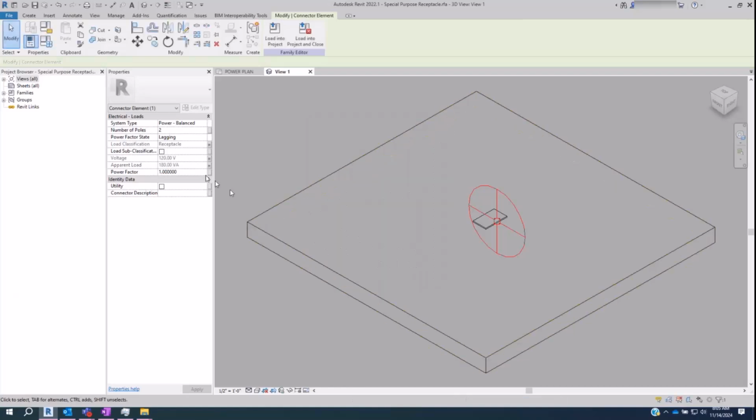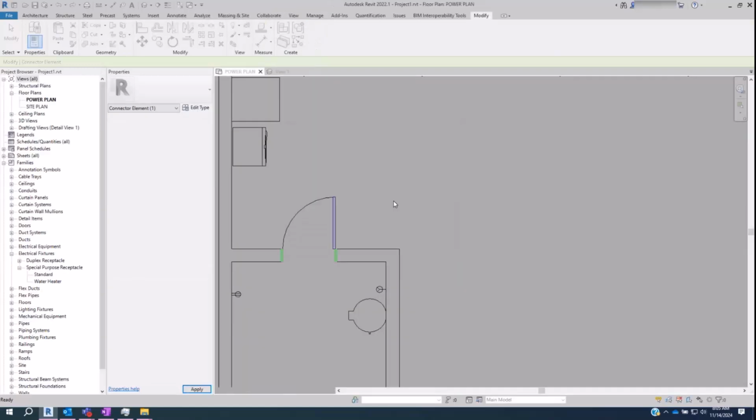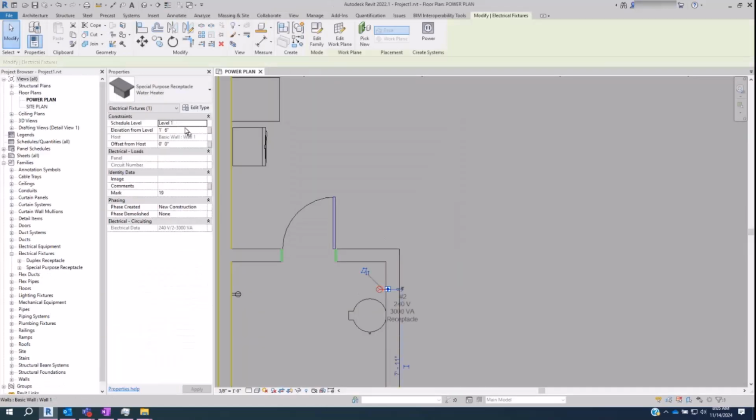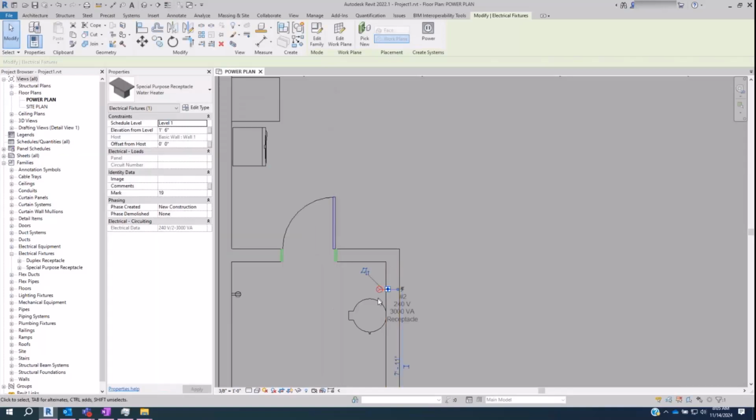And our power factor, which I think we talked about a little bit in previous videos. If you have not watched that and understood what power factor is, please go do that at some point too. Since these are straight heaters with no motor, no capacitors, no high frequency switching, the power factor will just be 1. So that's fine. Now our water heater load is 3 kW, 240 volt, 2 pole.